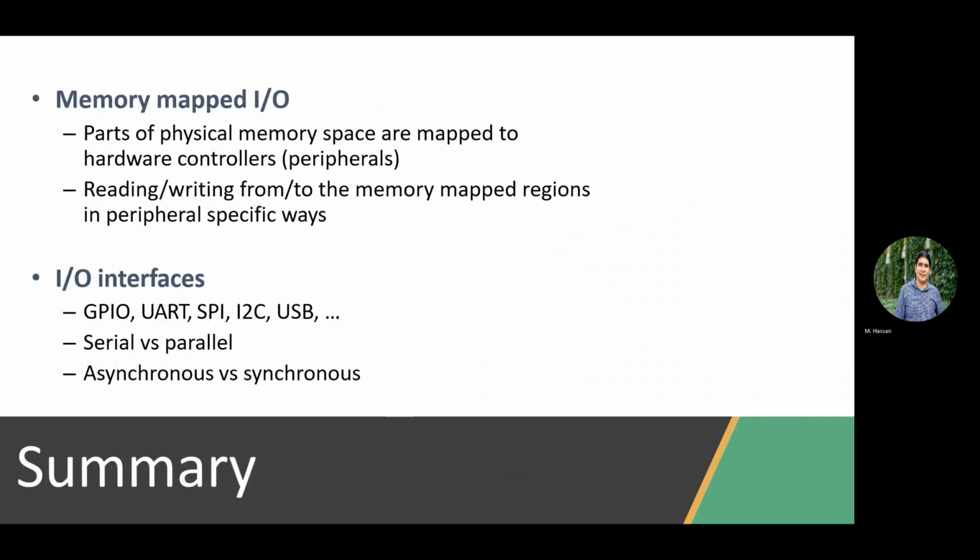Okay. So to summarize, we have discussed, wow, this finished very fast. That's good. So to summarize, we have memory mapped IO devices. This is the way that we abstract all the complexity of IO devices and how to deal with them into a CPU protocol. Like I map all my input output devices as registers in the memory, which means I can write legacy software to configure them, receive data from them, or send data to them. Good. This is what we mean by memory mapped IOs.